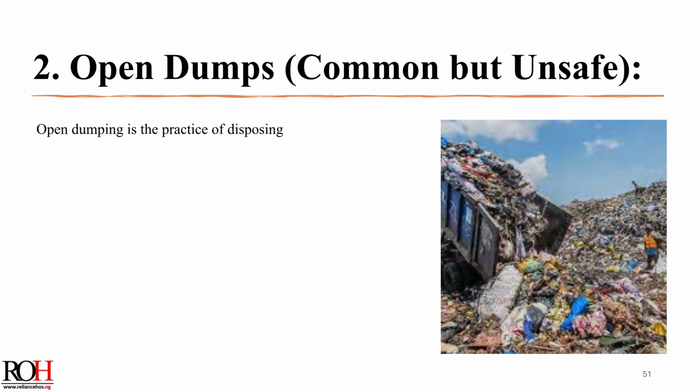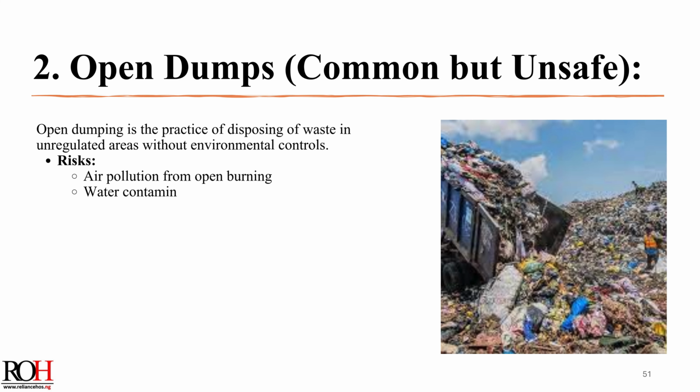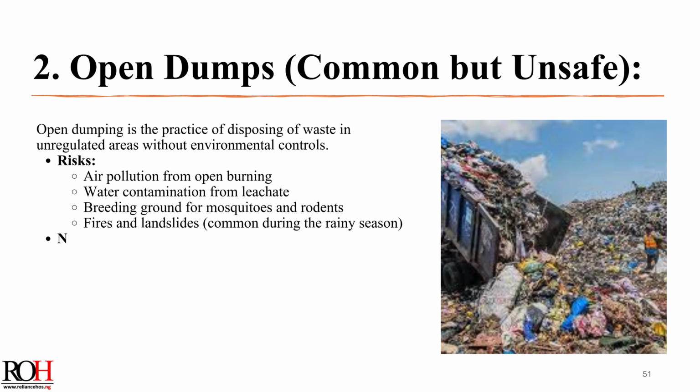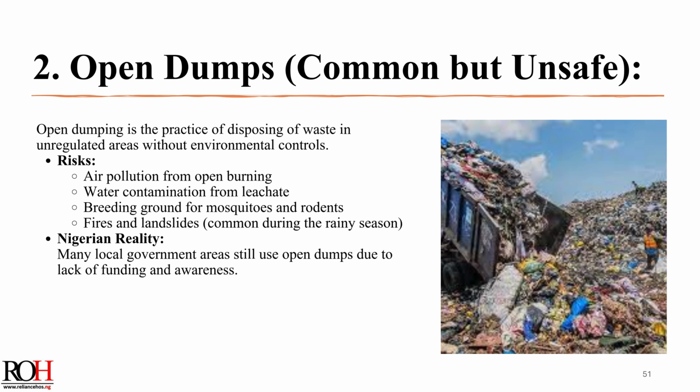2. Open dumps. Common, but unsafe. Open dumping is the practice of disposing of waste in unregulated areas without environmental controls. Risks: air pollution from open burning. Water contamination from leachate. Breeding ground for mosquitoes and rodents. Fires and landslides, common during the rainy season. Nigerian reality. Many local government areas still use open dumps due to lack of funding and awareness.